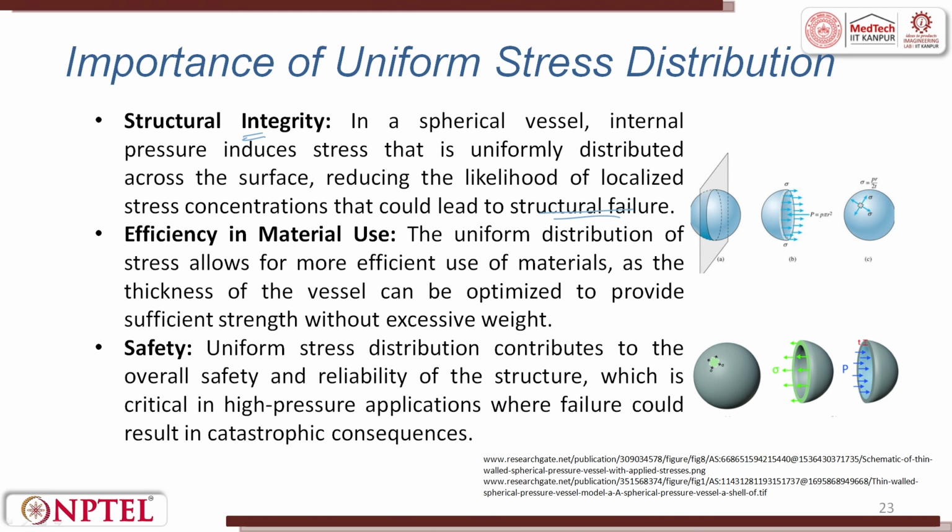Many times when we start machining a brittle material like glass, we take it inside a chamber wherein there is uniform stress distribution around the piece. So, there will be pressure at this point of the workpiece, this point of the workpiece. When I try to machine, it will try to convert the brittle fracture into ductile fracture.